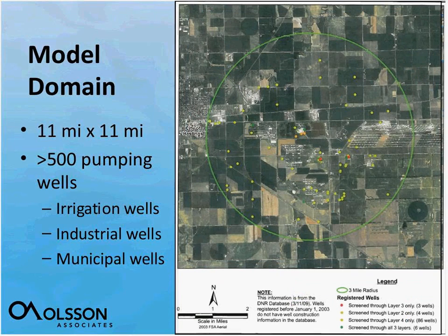One of the things we needed to find out, as I said before, was which layer these wells are tapping into. Now, we don't always have well construction information on every well out there. So what we did was we took all that we knew, that we had records on, and found out that all but 2 or 3 of the wells are tapping into the lower aquifer. The other wells were actually just monitoring wells, and they weren't even pumping wells. So substantially all the wells in this area are pumping from this lower aquifer.